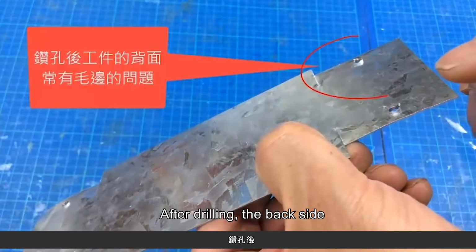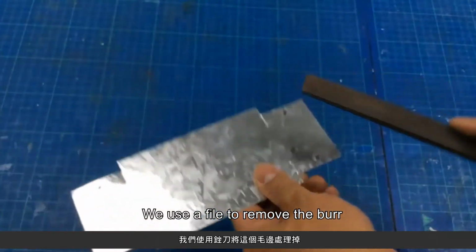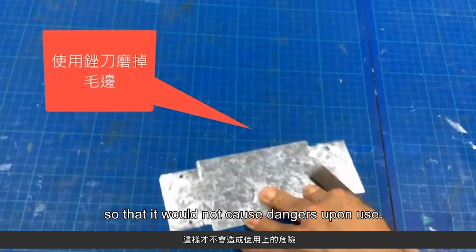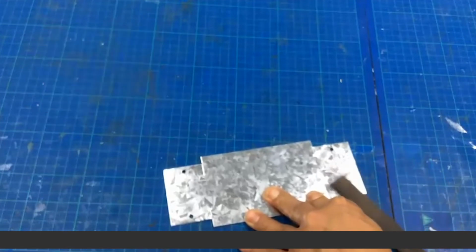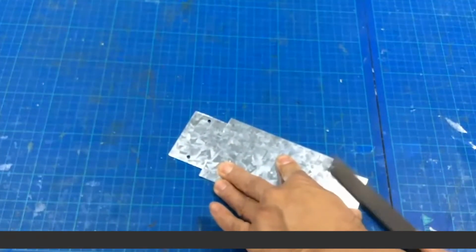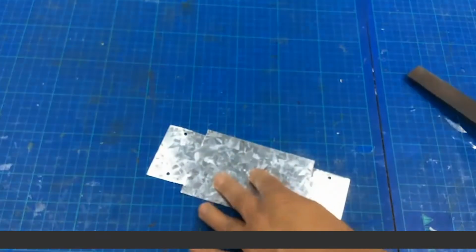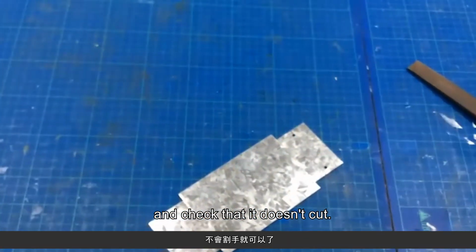After drilling, the backside of the plate often has the issue of protruding burrs. We use a file to remove the burr so that it would not cause dangers upon use. Let's just touch it with our fingers and check that it doesn't cut.